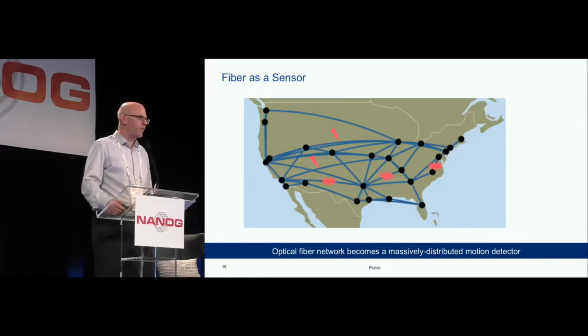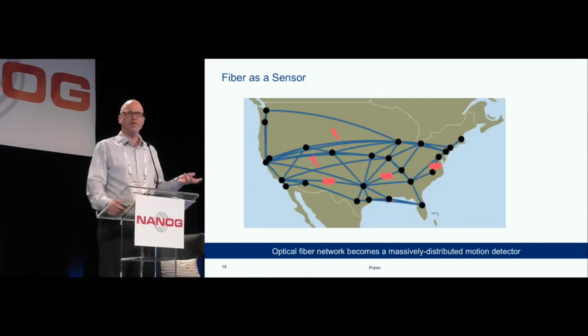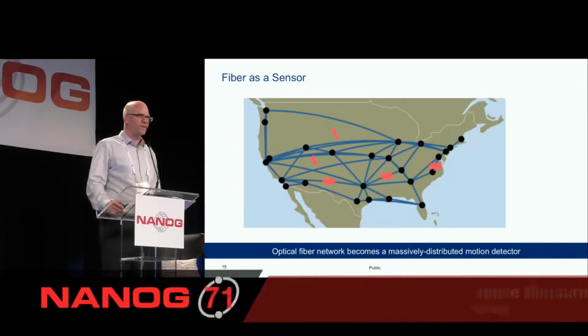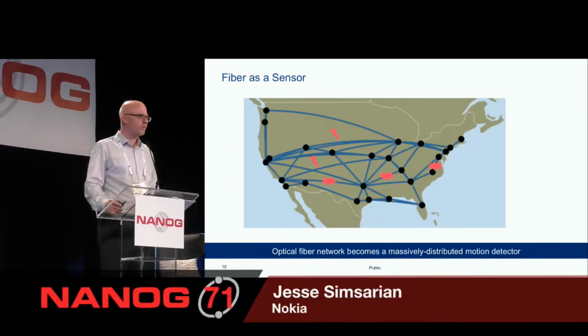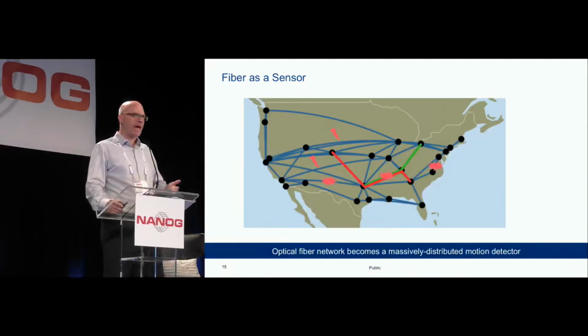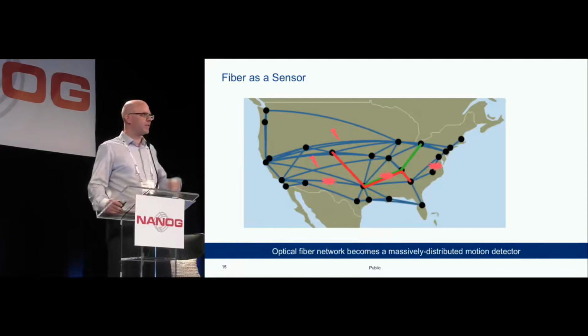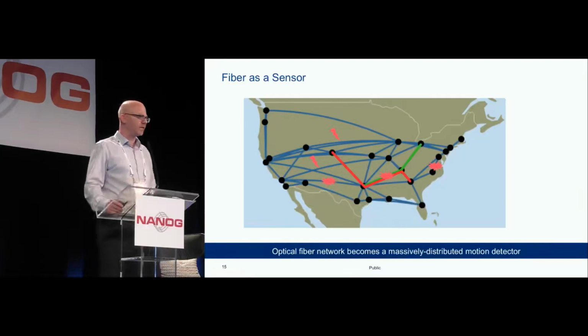So we have two different methods here. One is doing a span by span measurement of the polarization and looking for fast transients, and that gives you localization down to a span level. Alternatively, you could measure the polarization over an entire path in the network. That doesn't give you the same type of localization unless you start correlating it with other paths that have a problem, and then you look at the overlaps, and then you could try to localize where the problem actually is.